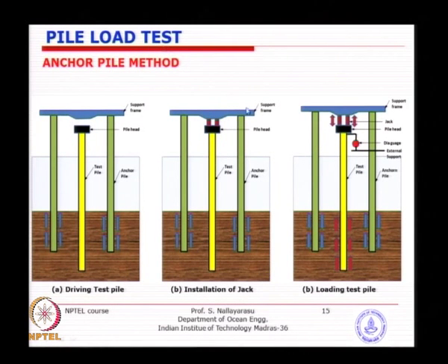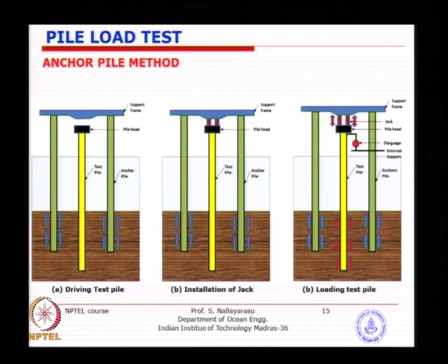Anchor pile seems to be very good, but then caution needs to be taken in terms of design. Make sure that when the pile is being tested, the anchor that you have designed is not moving too much, otherwise you will actually be measuring a relative movement of the anchor pile and the pile being tested.